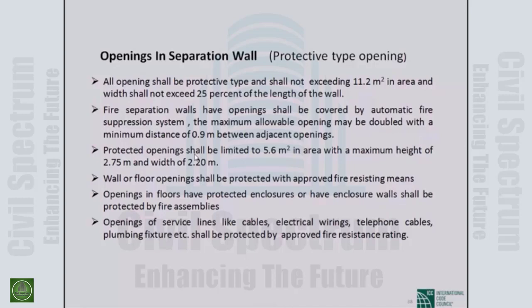Opening service lines like cables, electrical wirings, telephone cables, the plumbing lines, you need some fire protection. In some languages, it is said as a penetration, not the opening, it says some penetration. In BNBC, we do not define penetration, but in NFPA, it is defined as a penetration because this opening is small.